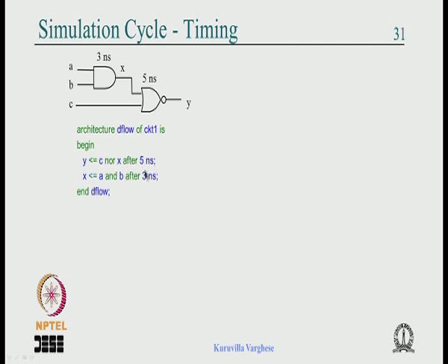If you give it to a synthesis tool, it is going to generate some circuit like this, ignoring this, which is not going to give any delay. If you go to FPGA it will map to some circuit, whatever may be the delay of the circuit you get, okay. This is not for synthesis, it is only for simulation, but if you simulate this circuit it will definitely show the output will come after 5 nanosecond delay, okay.